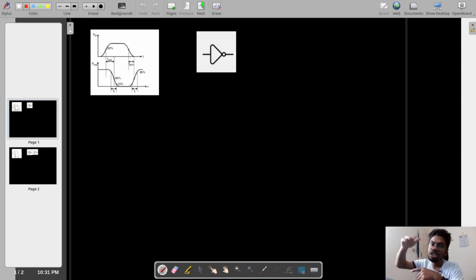And charging time capacitor, anytime we are going from 0 to high output, we are charging our load capacitance, and charging is mostly the current through the PMOS. So going from low to high mostly depends on the size of the PMOS, and the reverse is true for the NMOS. That's why these two sides won't be the same. So what we do is take the propagation delay as the average between the two, the low side and the high side. That is your propagation delay.